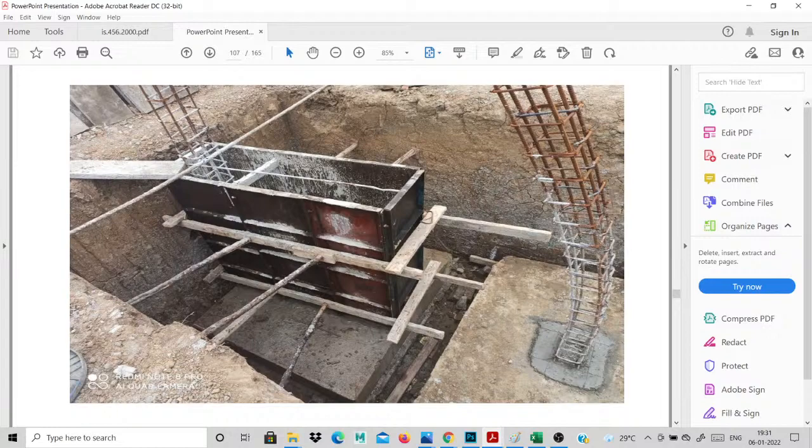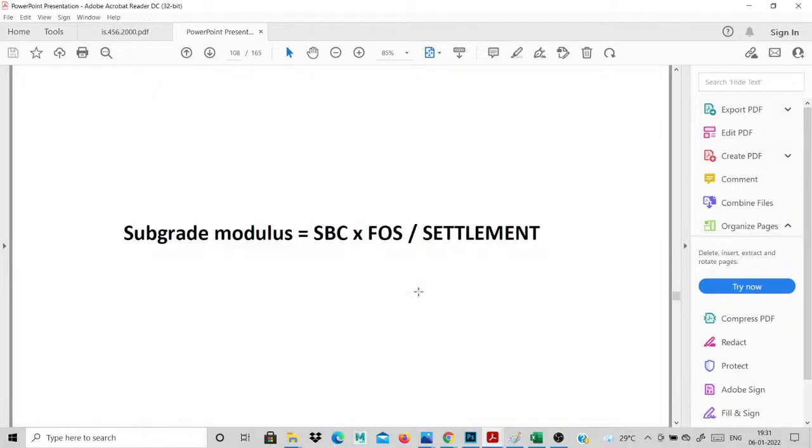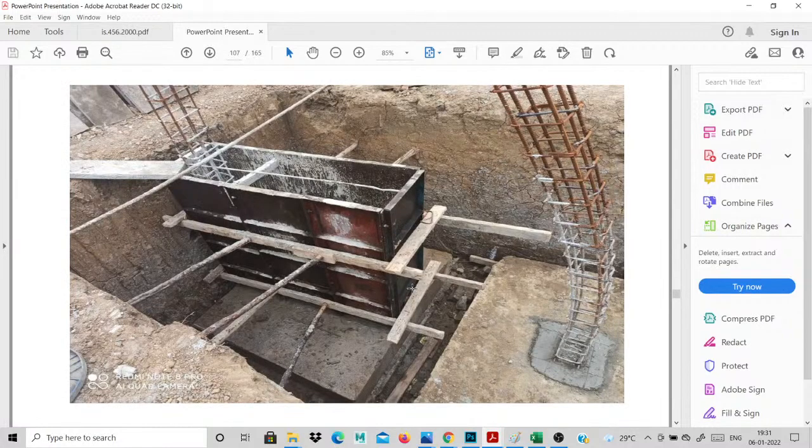It will be provided. This beam is connected with one end to a column, the other end to the pedestal edge. There is a main one. Two types will be used for this eccentric footing. One is connected with a column, and the other side is also connected with columns. The other type is connected with a column at one end, and the other end is ended at the pedestal edge. That type of ones. Okay.